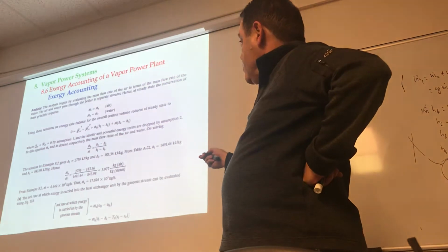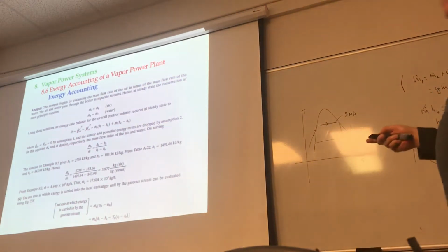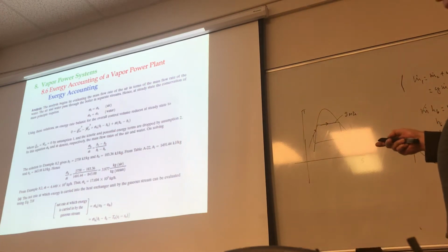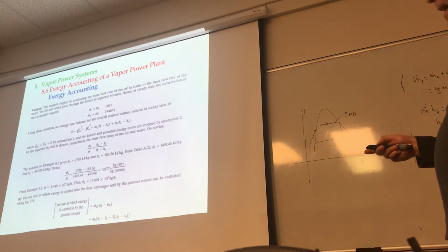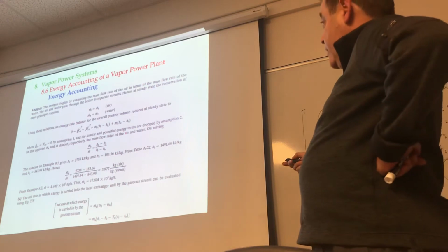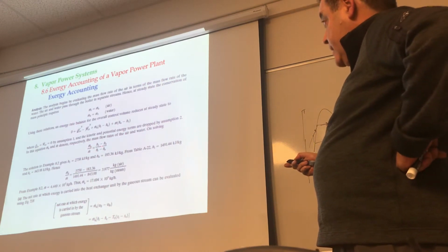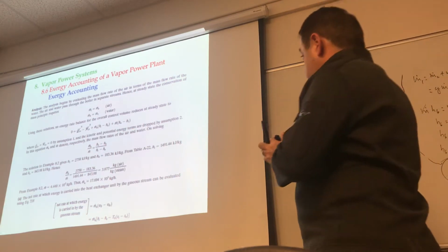That's just the first law of thermodynamics applied to the open system, okay? And we neglected, obviously, change in kinetic energy and change in potential energy here. In this equation, m dot a and m dot w denote respectively the mass flow rates of air and water, which can be solved by